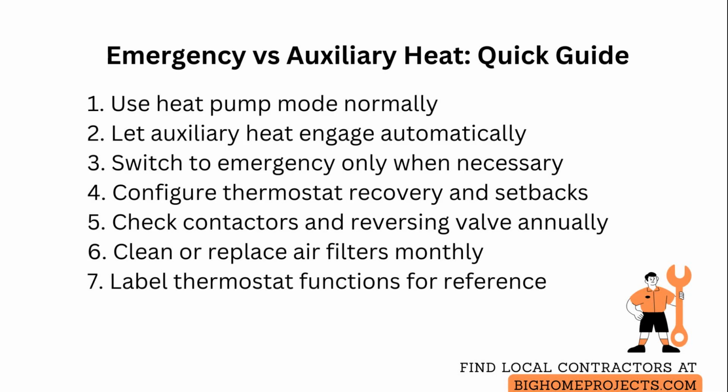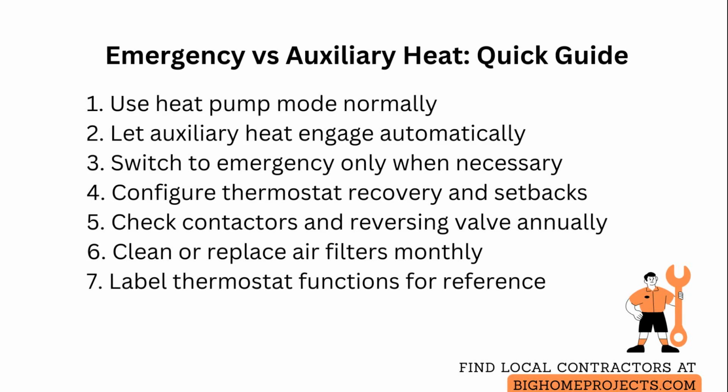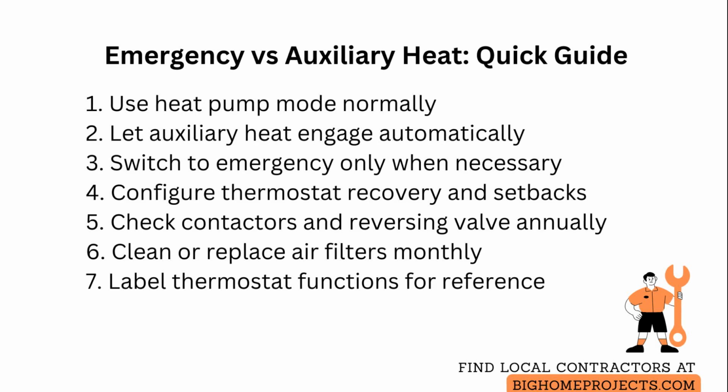Auxiliary heat is an automatic supplement that kicks in when the heat pump cannot meet thermostat demand during very cold weather. It stays off as long as the heat pump can maintain set temperature, which preserves efficiency.